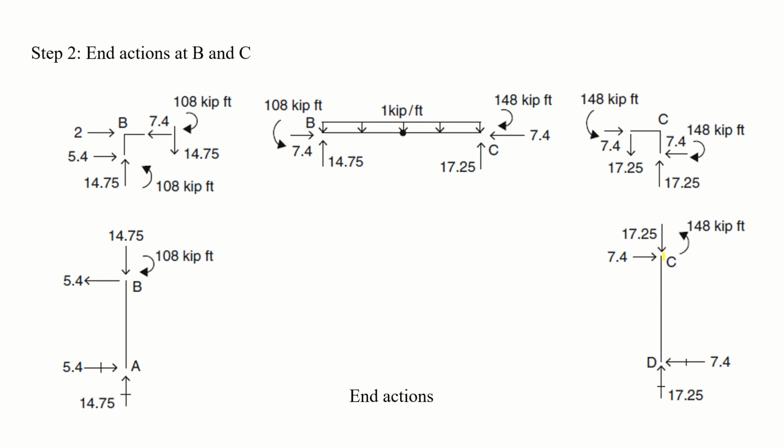And what will be the value of bending moment? We know the direction of this bending moment. It is causing a bending moment in the clockwise direction, and to resist this bending moment, the same bending moment will be generated at point C in the anti-clockwise direction, as you can see.